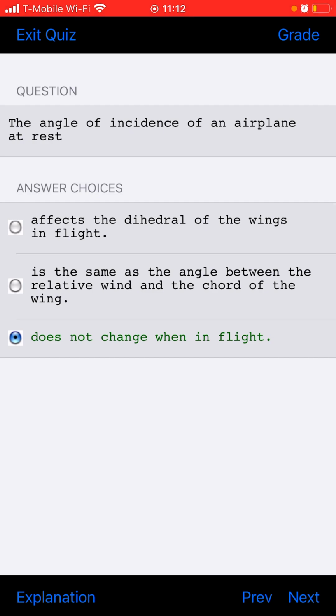The cable-operated control system of an all-metal aircraft not incorporating a temperature compensating device has been rigged to the correct tension in a heated hangar. If the aircraft is operated in very cold weather, the tension will decrease when the aircraft structure and cable become cold.